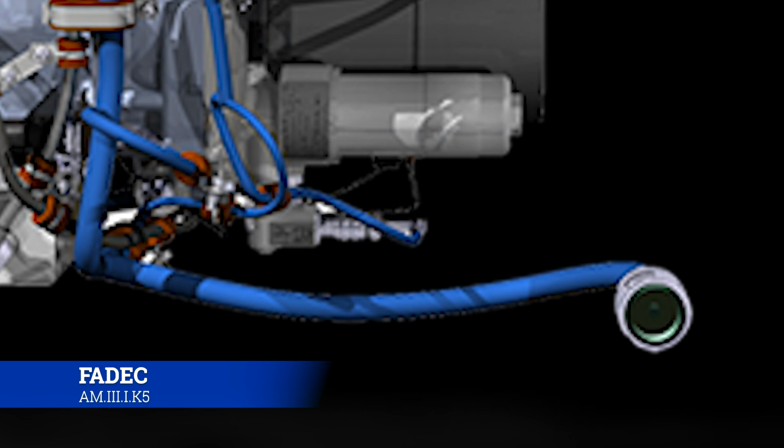And the idea behind it is that if we can give the FADEC system its own electrical power source, then if we have an engine out or something else like that, it'll be okay. We could lose all of our electric systems, but in theory, the FADEC will still be able to operate because it has its own PMA and its own circuit outside of everything else.